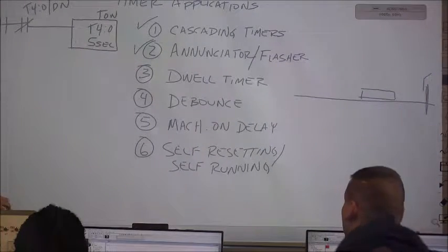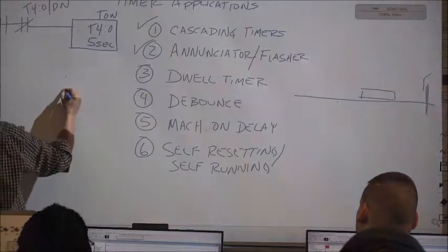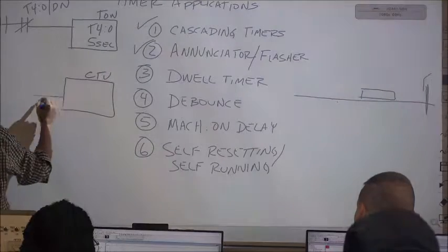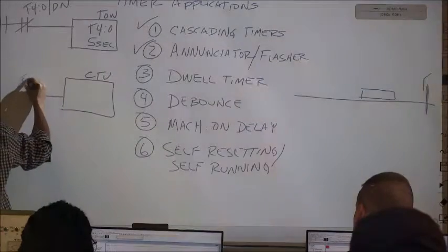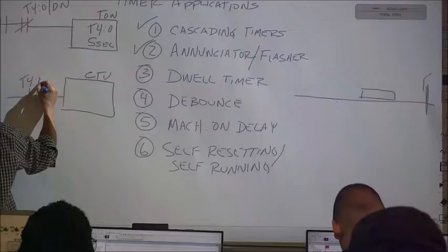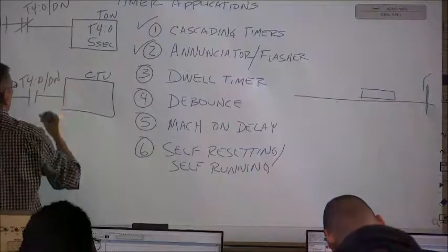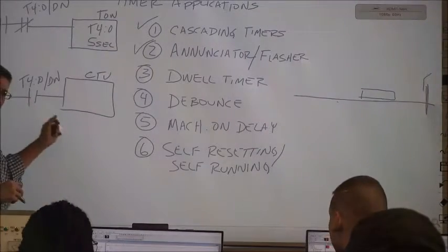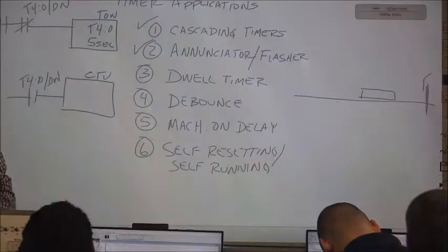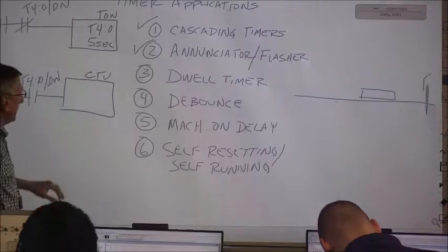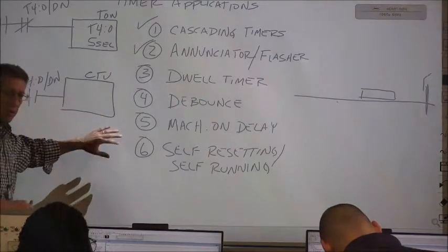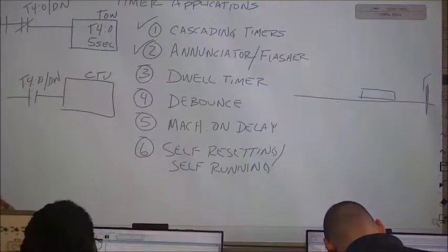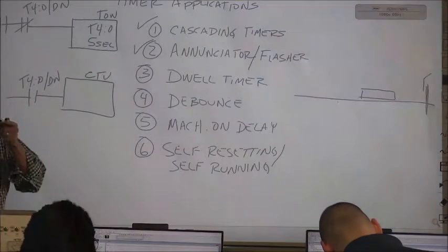And generally what we do with this is we increment counters. The CPU takes the done bit, although we haven't talked about counters yet. But we're incrementing this counter every 5 seconds. So we can set up a minute counter, an hour counter, a day counter, and so on. Basically make a clock.